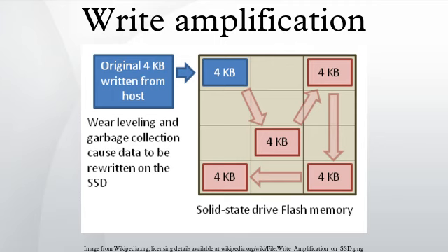If this additional space can be identified by the SSD, perhaps through continuous usage of the trim command, then this acts as semi-permanent over-provisioning. Over-provisioning often takes away from user capacity either temporarily or permanently, but it gives back reduced write amplification, increased endurance, and increased performance.